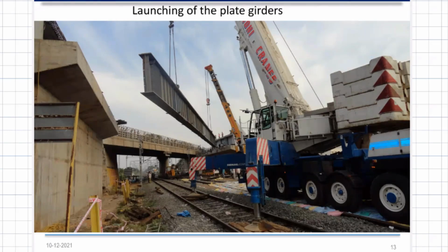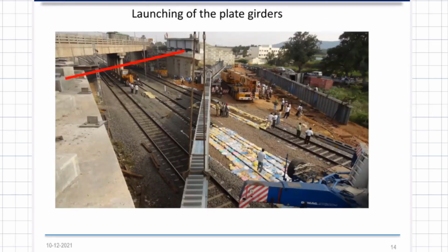You can see here, this first girder, the other girder is ready. You have 2 cranes lifting in tandem, one here, one there. Then the red line is where I intend to place this. Usually we'll start from the extreme one, and then we keep on adding towards the lifting side, right?